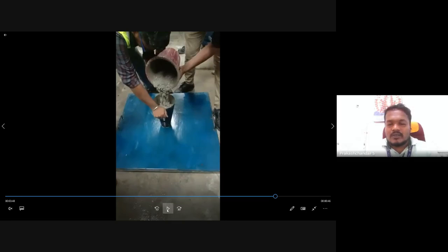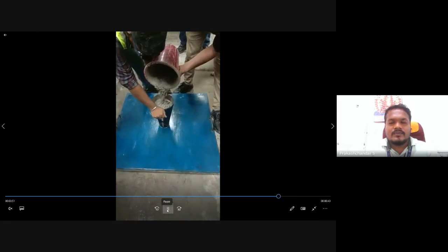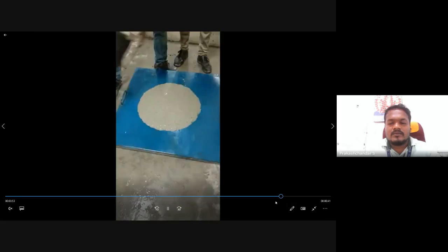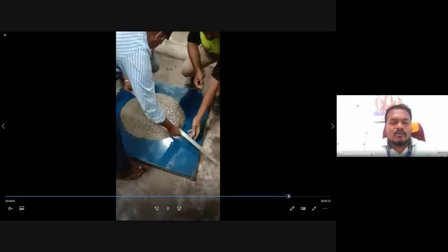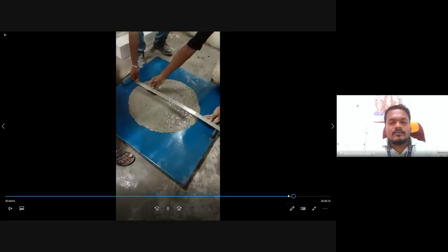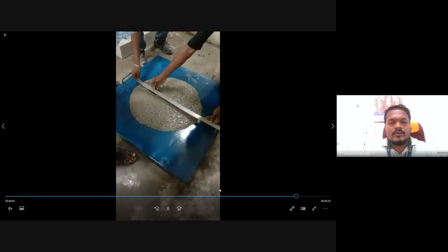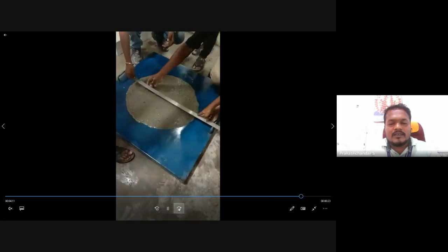Okay, the next test is the slump flow by Abrams cone test. This is also filling ability. Fill the concrete, then remove the cone and measure in 4 directions the diameter of the concrete spreading. You can get values here of 650 mm to 800 mm.